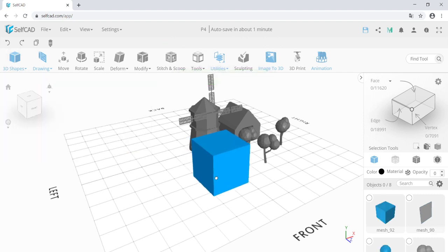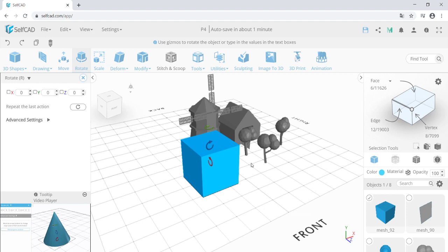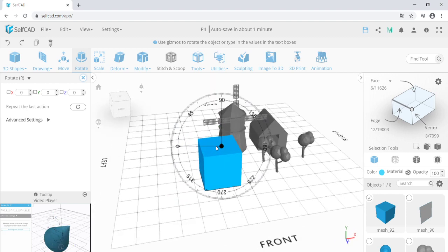Okay, so the compass, I call it the protractor actually, has this kind of logic where if you are in the center of the protractor or the compass, it actually has a 22.5 degree step, which allows you to set the positions like 45, 90, and so on easier. So the thing that you need to do is go out a little. Now you can actually see that the step became 1 degree, and you can set your rotation much more precisely.